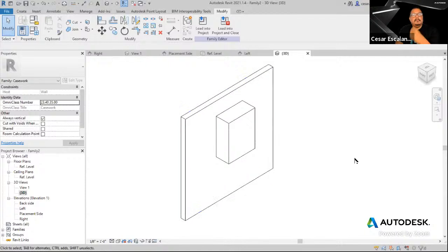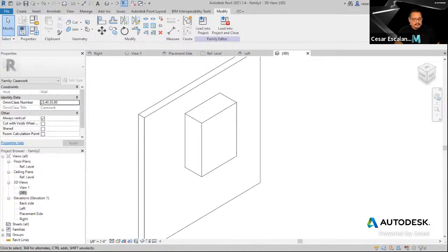On a 3D view, so what's next? We're going to define the material of this solid. And we're going to make sure that somebody in the project has the ability to change it. Then we're going to carve out the solid with another solid. And we're going to basically make the hole out of it. Then we're going to bring the doors and we're going to bring the shelves. Okay, so let's talk about the material first.